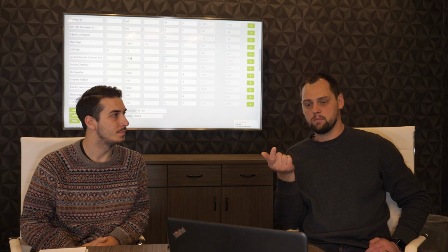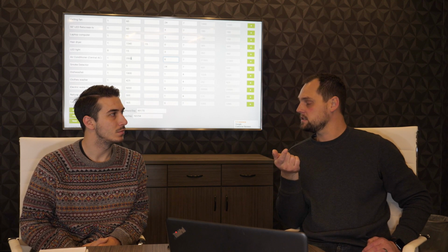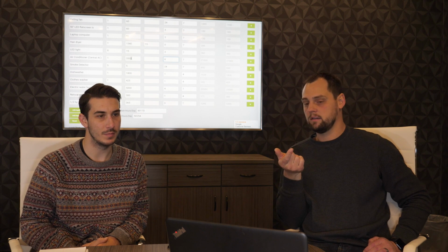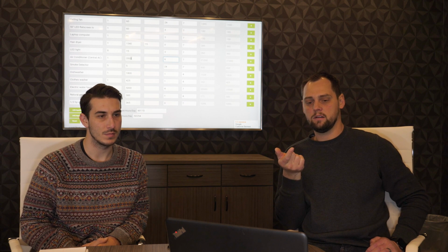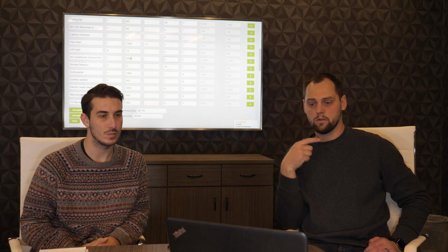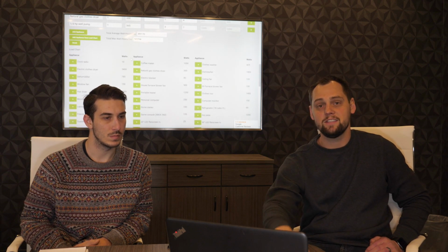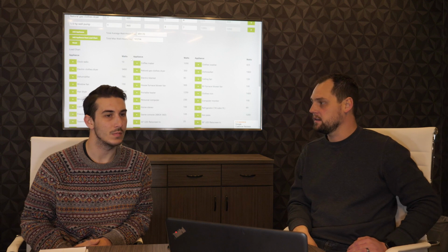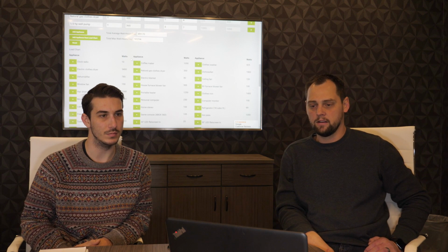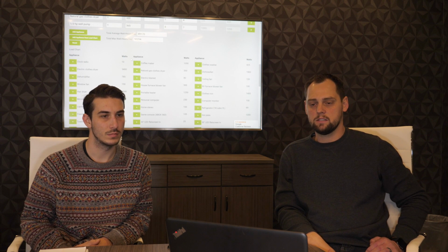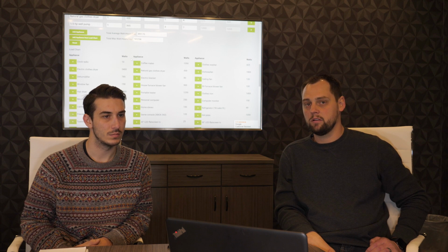The problem is, if the air conditioner and the hot water heater are running at the same time, you're right at the stretch of your limits for an 8K inverter, so you're probably going to need something more than that. This value here, being that it's 50 kilowatt hours, it'll almost guarantee you a 48 volt battery bank. Absolutely. There's really no better way to do that. 8 to 12K, and it really depends on the model of the air conditioner.